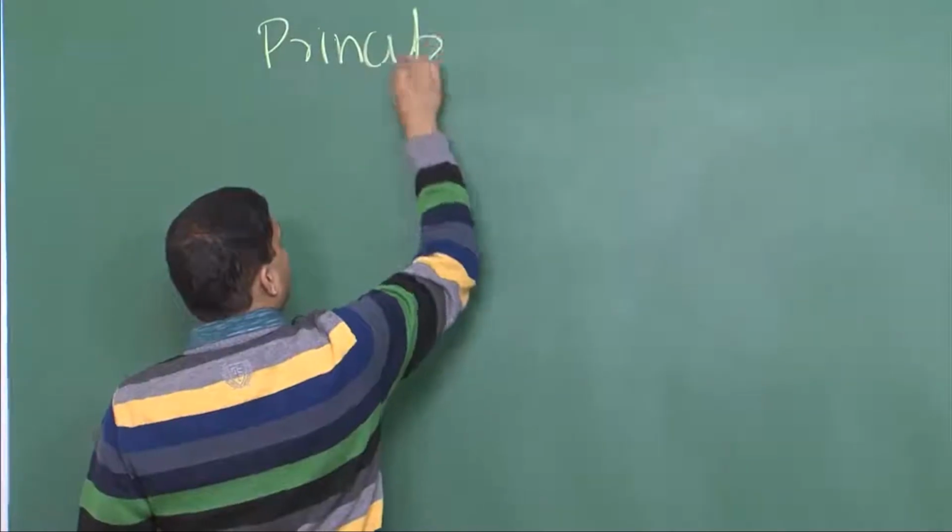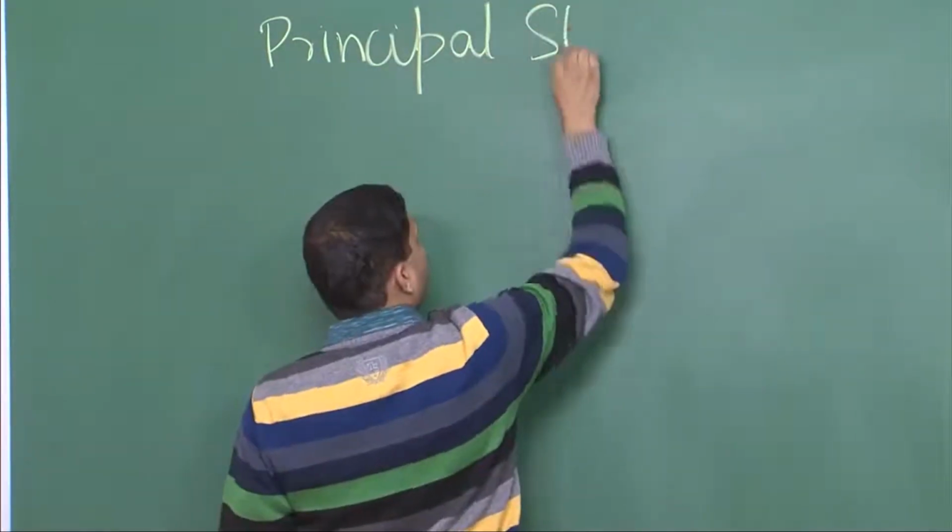Okay, so welcome back, and we were discussing stresses and strains in individual elements of a component. We saw that even though you may start with an element that has only normal stresses, if you rotate the element you can have normal as well as shear stresses. Now, the inverse is also possible, where you have a combination of normal and shear stresses, but you can rotate it to a position where you have only normal stresses, and these are called principal stresses. So, we were talking about principal stresses.